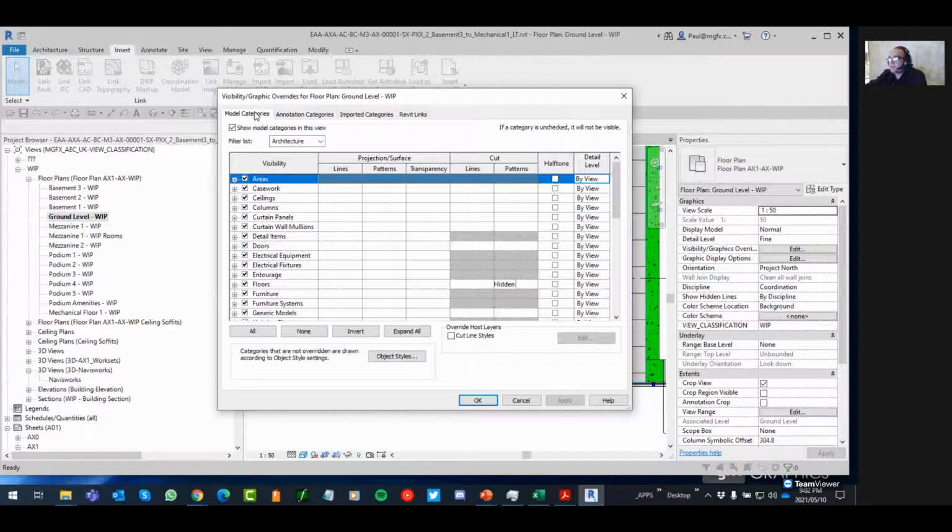Firstly, none of the worksets are available for us to manipulate, so we would be unable to switch worksets on and off. On large models, this is critical because we manage the size of the models using worksets that our computer has to process.